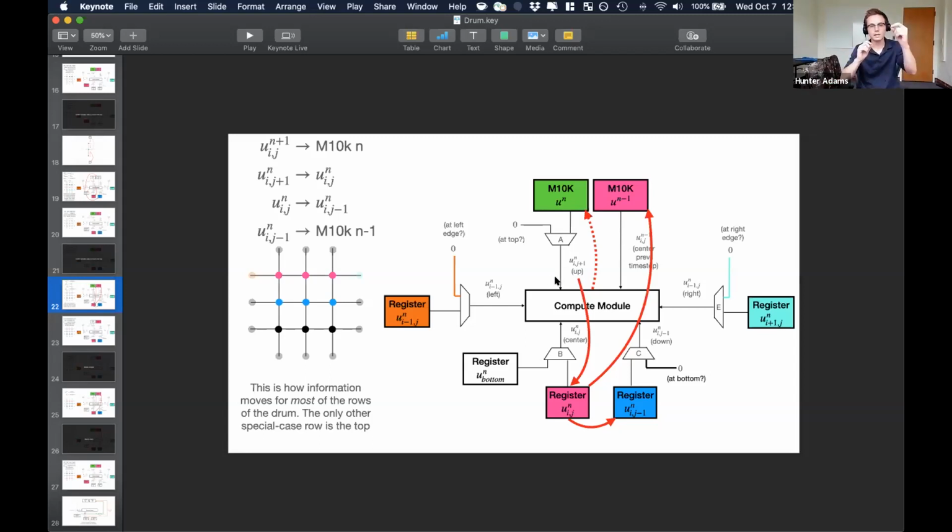And then start by building a state machine in which you attempt to start at that bottom row, read out of the M10K block directly above it, leave out the compute module at first, and just see if you can then move to the next row and properly move what was previously in the top node register into the center, what was previously in the center node register into the bottom, and then read out the new top node. And put all of that out through a ModelSim test bench. So put out the registers that are holding the top, center, and bottom nodes.